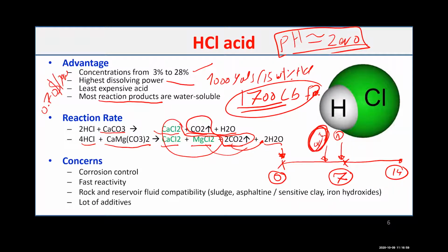That's an important part to have when you do the flowback of the acid. When you are evaluating the acid flowback, you would like to see this pH coming back and to understand how effective it has been. If you have anything in the formation that can affect the pH, it also affects the corrosion.